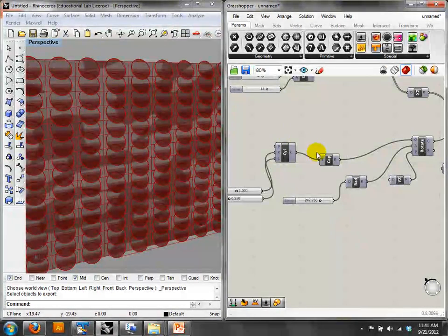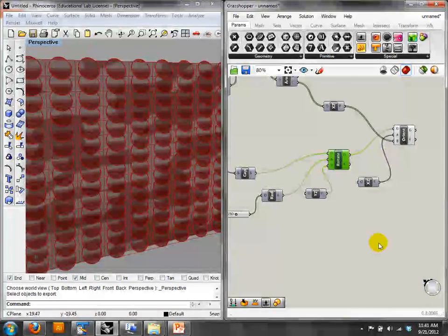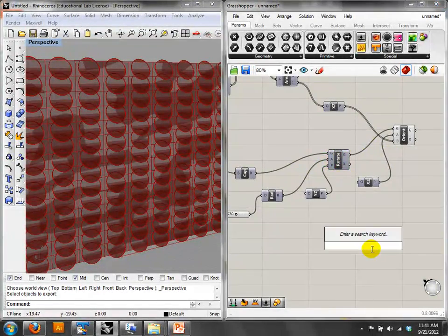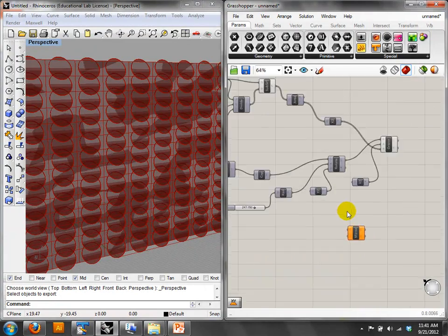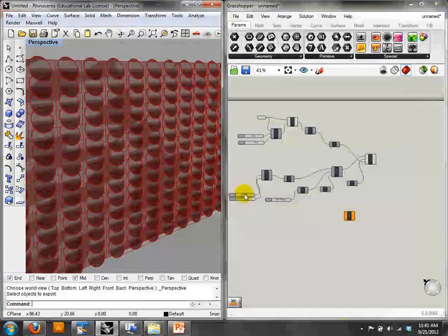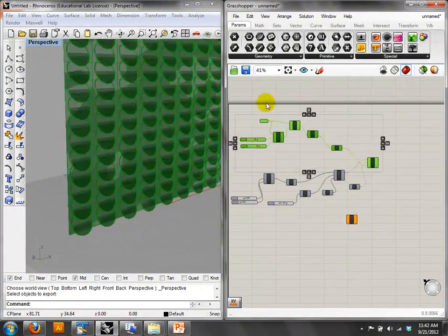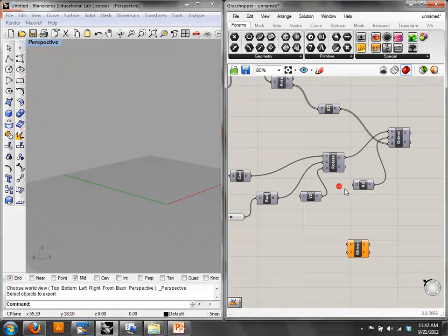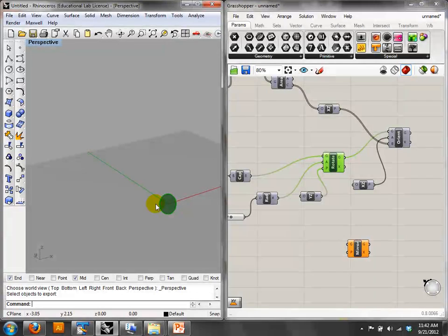Okay, so we've created the cylinder, we've capped it, we've rotated it. Then I want to make a copy of it that's flipped, and I would do that after I've done all this stuff, basically. Turn all this off now. This is just about creating this one object that you're going to copy that's parametric.